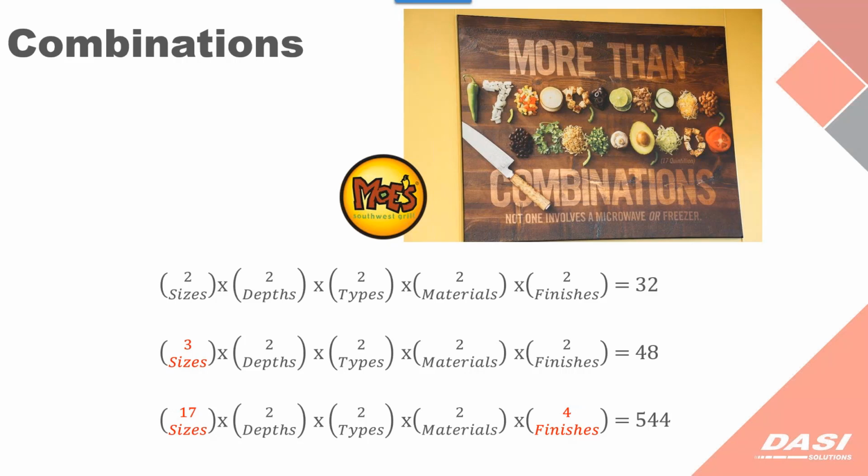And that really affects our SOLIDWORKS models and the assemblies that those models might go into. As just a reference here, I looked at the properties of the file after each step of this. If I had no configurations in the model, it's about 93 kilobytes, and then it grows pretty rapidly. When I had the 32 different models, it was 515. We got close to 2 megs when we get to 48, and then we have about 20 megs when we get to my full socket set.